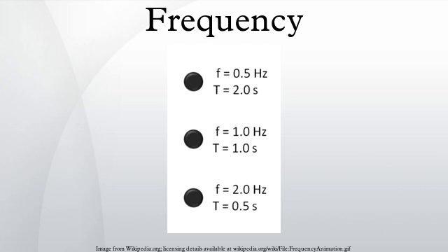If the two signals are close together in frequency, the heterodyne is low enough to be measured by a frequency counter. This process only measures the difference between the unknown frequency and the reference frequency, which must be determined by some other method. To reach higher frequencies, several stages of heterodyning can be used. Current research is extending this method to infrared and light frequencies. Frequency of waves: for periodic waves in non-dispersive media, frequency has an inverse relationship to the wavelength, λ. Even in dispersive media, the frequency f of a sinusoidal wave is equal to the phase velocity v of the wave divided by the wavelength λ of the wave.